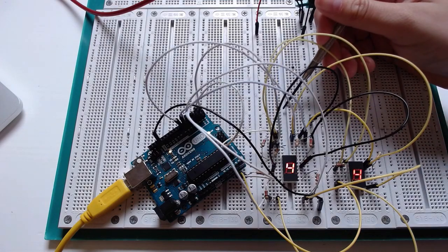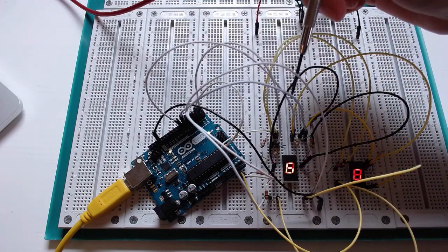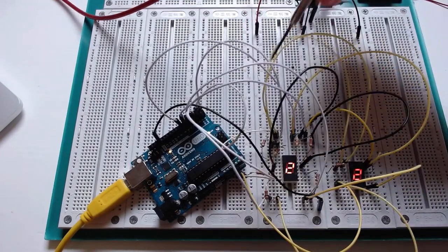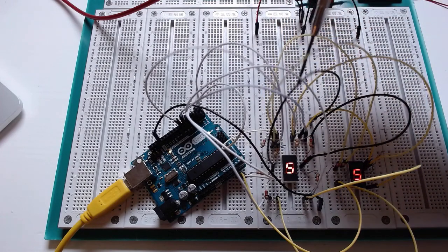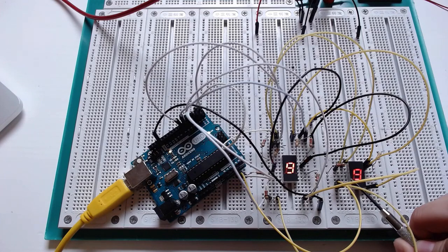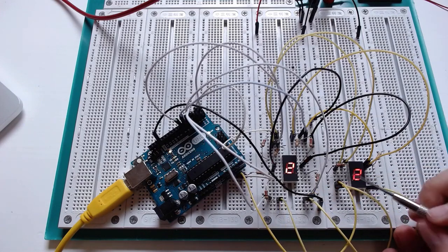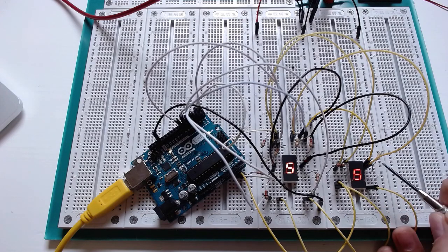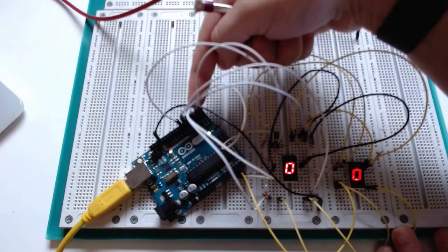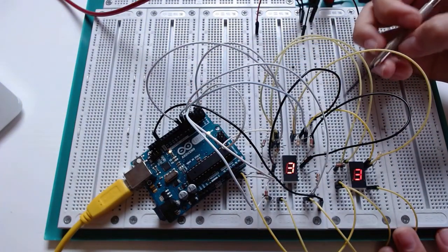This one is hooked up properly. All of the white wires that come out of the Arduino, each one corresponding to a different segment, is routed through a resistor to the anode pin of the display. That's exactly how it should be wired up as previously mentioned. What's different is that this display on the right has just the cathodes with resistors. All of the other wires, these yellow wires, are going directly to the Arduino itself.